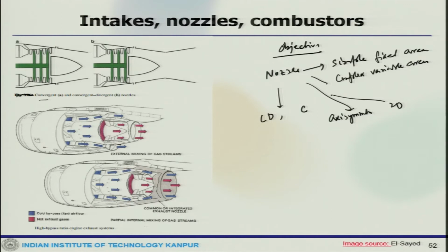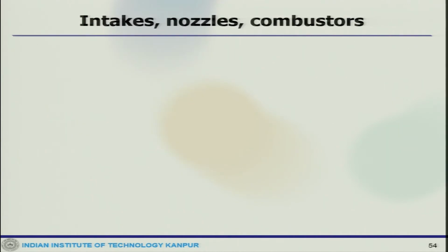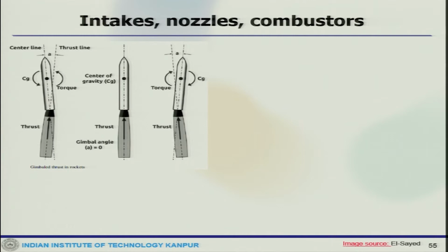Now, rockets also have alternative options for nozzles; there are different possible nozzles used in rockets. The middle rocket shows a normal flight configuration. If the nozzle is deflected to the left, then the thrust vector generates a torque about the center, and so on. So, now you have the operation of nozzles.